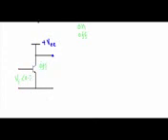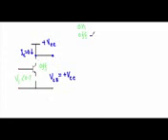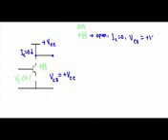When the transistor is in off state, the collector and emitter terminal gets disconnected from the circuit. Therefore, this transistor will act as an open switch. Therefore, the collector current IC will be equal to 0. As the collector current becomes 0, the voltage difference between the collector and emitter terminal, VCE, will be equal to plus VCC. So when the transistor is in off state, I can summarize it: our collector and emitter terminal will get opened, and the collector current IC will be equal to 0, and the collector to emitter voltage VCE will be equal to plus VCC.